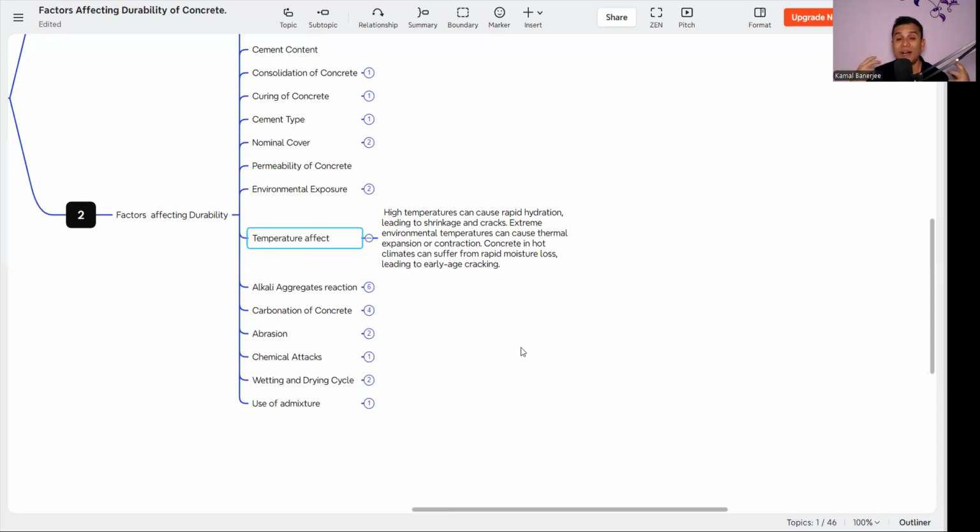Nowadays we are doing mass concrete, with temperature control and temperature monitoring. We need to know that if our concrete is mass concrete, we need to prepare a low temperature concrete at the time of pouring, and also we need to protect the concrete for the entire period when the heat of hydration is generating, so that there will be no thermal cracks. So what is mass concrete, what is the thermal gradient, and what is the temperature control and monitoring process?